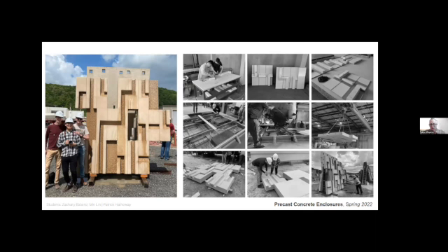This is interesting because we tend to take advantage of the things that most architectural precasters offer. In this case, you can put retarder on the concrete, as you can see in the image on the left, and then wash away the part that is not cured, and expose the aggregates and create, with the same cast, very different colors and finishes on the surface. So again, that's for all students. Most of them have no idea about precast. They really learn about the material, the possibilities, and what is possible, right? Mostly from a design standpoint, but also from a performative standpoint.